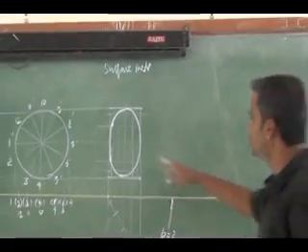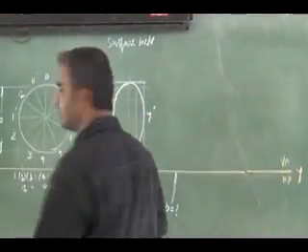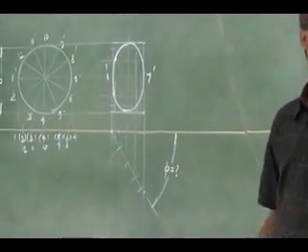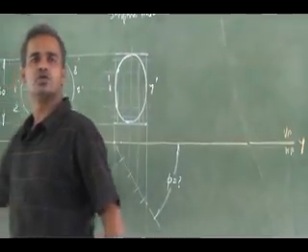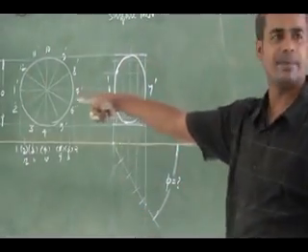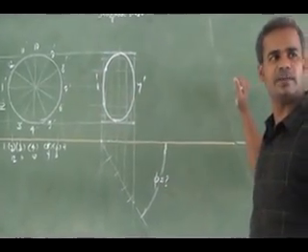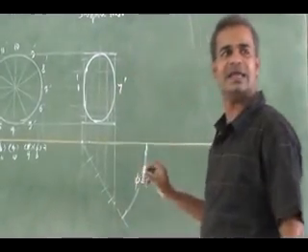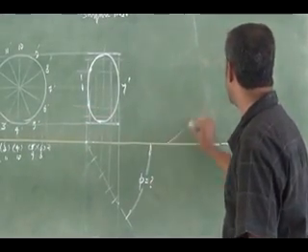Now which one do I have to tilt to phi? This one. This is my 1 dash, this is 7 dash. This one I have to tilt to 35 degree. If it is an apparent inclination alpha, straight away I can redraw it, similar to the last class problem. Now it is not an apparent inclination, it is a true inclination. Again, be careful in this step. You see here, what you have to do is just draw a 35 degree construction line. It is for this inclination. I am drawing a 35 degree construction line.